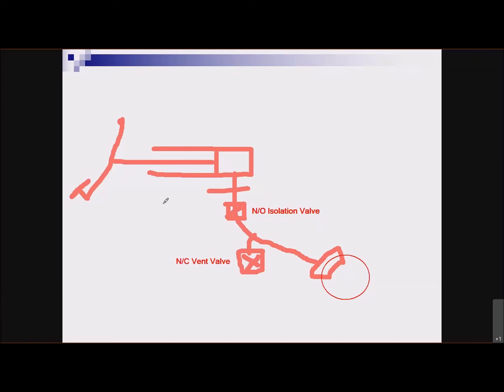We block off that valve again, effectively cutting off any more pressure from your foot from hitting that brake. And because that solenoid may be opening and closing relatively rapidly, it's stopping your foot from going down, but then it's letting it go down, then it stops it, then it lets it. You may feel a pulsation in the brake pedal. You may hear it.